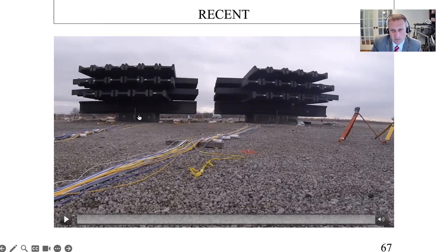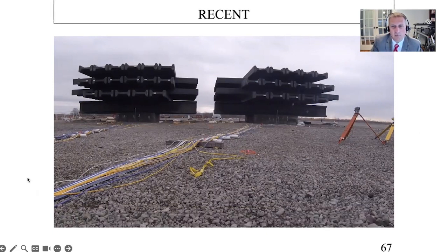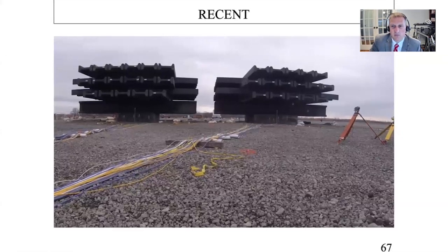Here, these small devices are displacement transducers that are measuring the amount of soil deformation at different depths using Borros anchors. And then we have an Invar rod here to measure how much the pile cap moves, so some surveying measurements are out here to look at that. I'll show this blast from this angle just to see it in a slightly different viewing geometry.